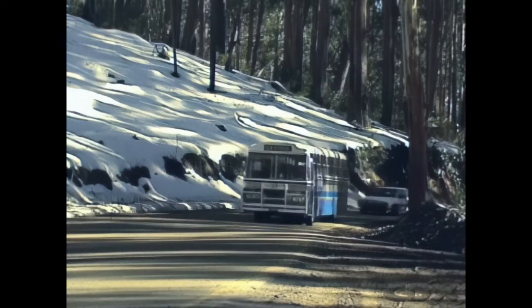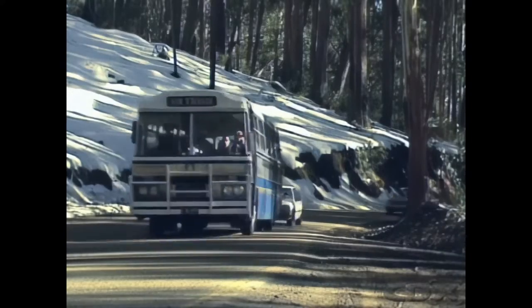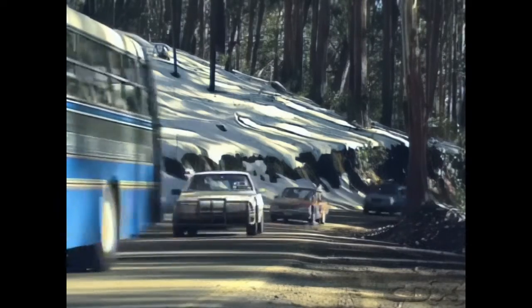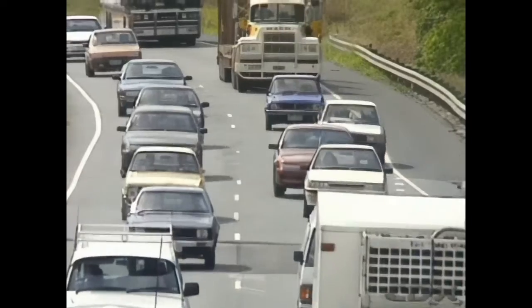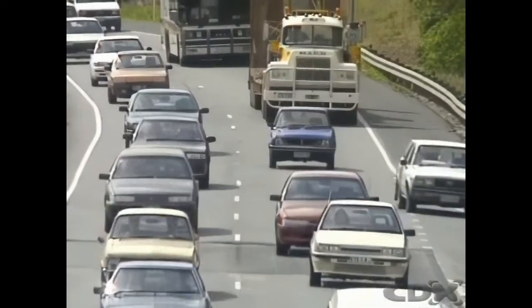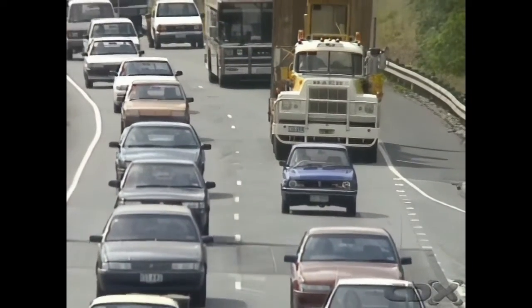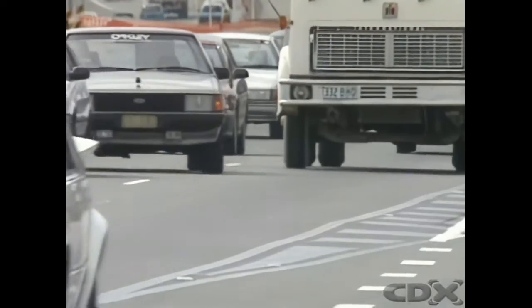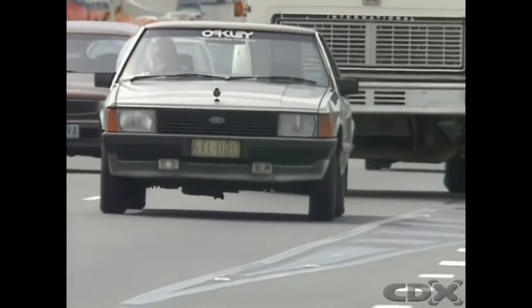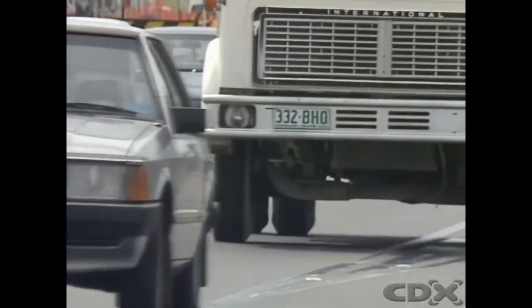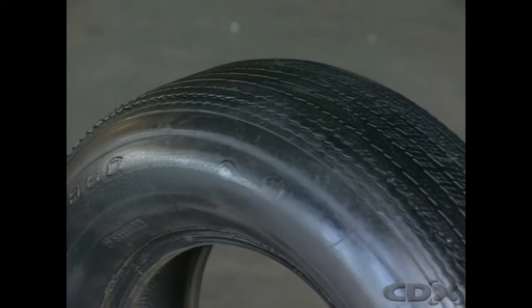However, during cornering, stiff sidewalls can distort the tread and partially lift it off the road surface, and that reduces the friction between the road and the tyre. Stiff sidewalls can also make tyres run at a high temperature. This is because as the tyre rotates, the cords in the plies flex over each other, causing friction and heat. And a tyre that overheats can wear prematurely.